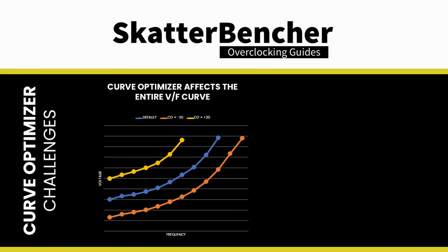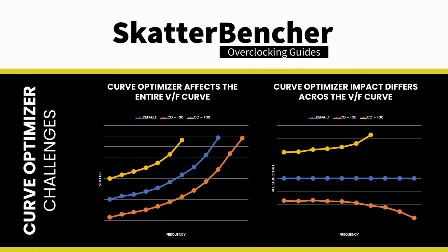It's a win-win, though there are a couple of caveats when it comes to using Curve Optimizer. Curve Optimizer impacts the entire voltage frequency curve. So it affects the stability across the entire range of operating frequencies from 600 to 6000 MHz. The same curve optimizer value also impacts differently across the curve.